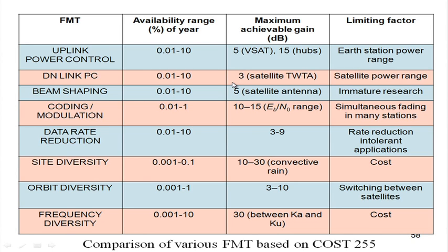So even with a 3 dB increase in EIRP, you do not enter into the nonlinear region. 99.99% of the time you are operating normally, and only 0.01% of the time you will be introducing this fade mitigation. The rest of the time you will be operating at 3 dB less power, and to compensate for the fade you use the additional 3 dB only during this time. Not very advantageous, but this is possible.